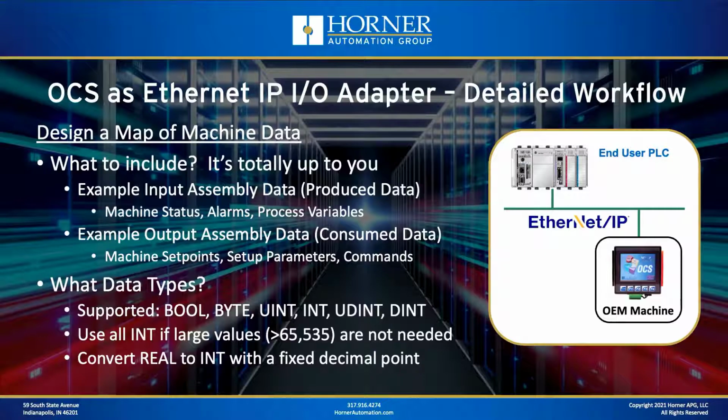But what about floating point data, you say? Well, floating point data isn't officially supported by Ethernet IP, but you can support that simply by converting any real data that you have over to integer data with a fixed decimal point. Let me give an example.